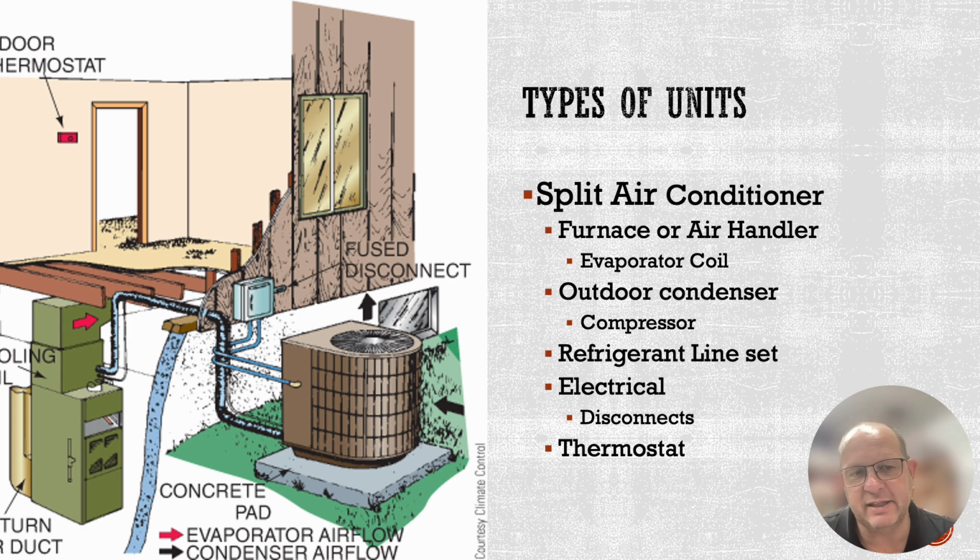In the picture that we're looking at to our left, what we have there is a condensing unit that's sitting outside. We have our interconnecting tubing for our refrigerant going to a coil that's sitting on top of the furnace. And then here is our evaporator coil on the inside. Now, this may be ran in a crawl space. This may be ran in an attic for our ductwork, or the system may be put in a closet and then used in an upflow manner or a downflow manner for the air that's moving through that system itself.